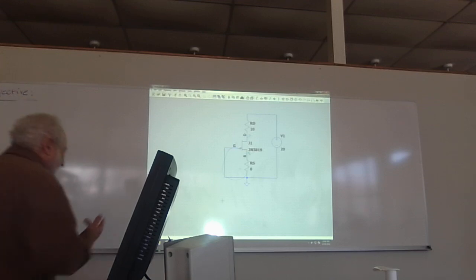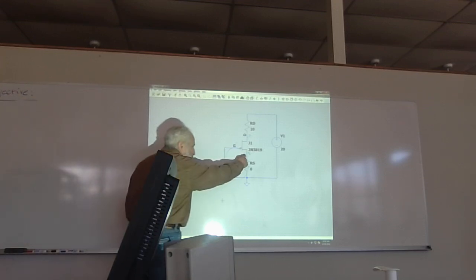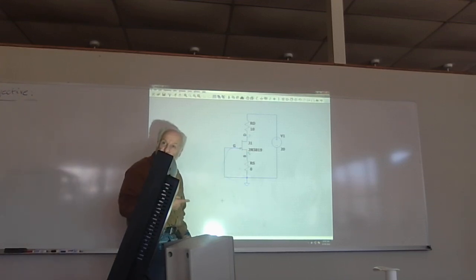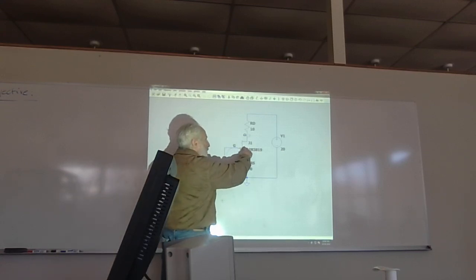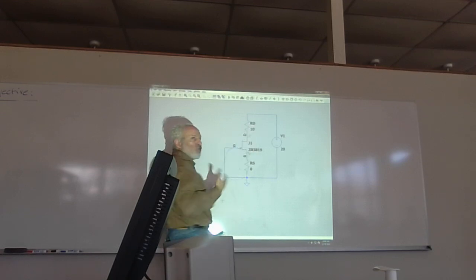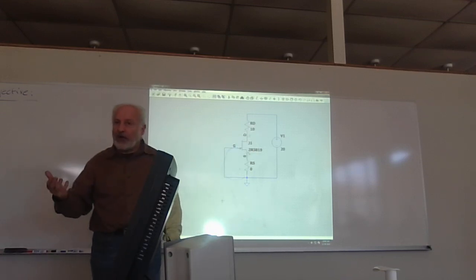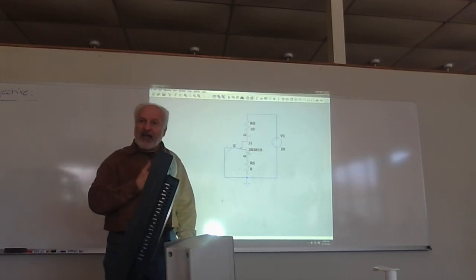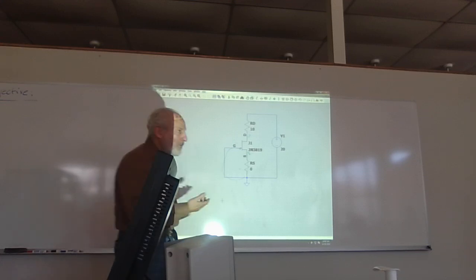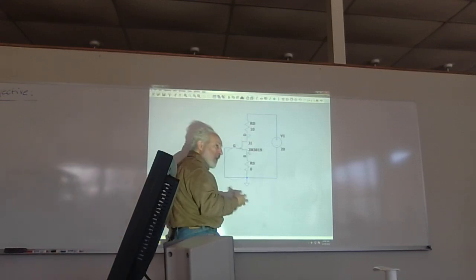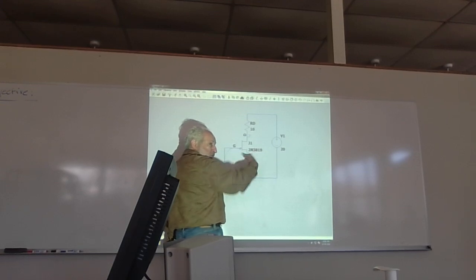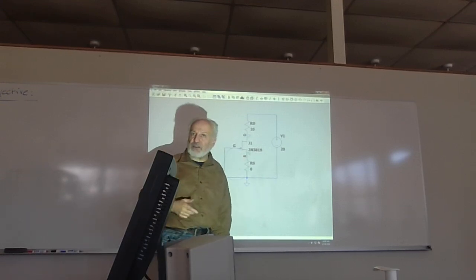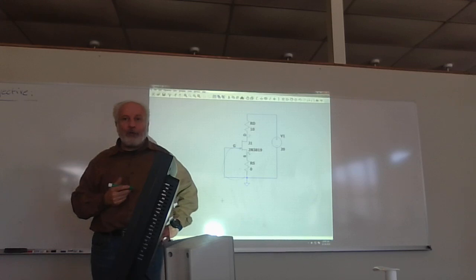So we know that Vx, the voltage from here to here, is going to be 0 because the resistance is what? 0, right? So I'll have maximum current going through here. I only have that resistor there just to limit the amount of current. Do you agree? I can take it to 0 as well and see how much real maximum current this thing can handle at 20 volts. You can experiment with that if you want to. I'm leaving the 10 ohm in there to start my lab anyway.